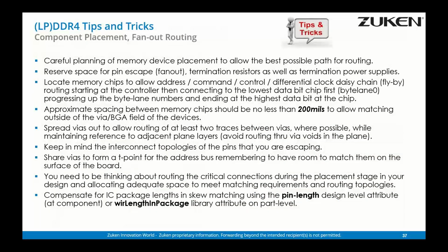To give you some tips and tricks, there are some issues which should be implemented, some routing recommendations like what is the proper order according to the different byte lanes if you have more than one memory chip.